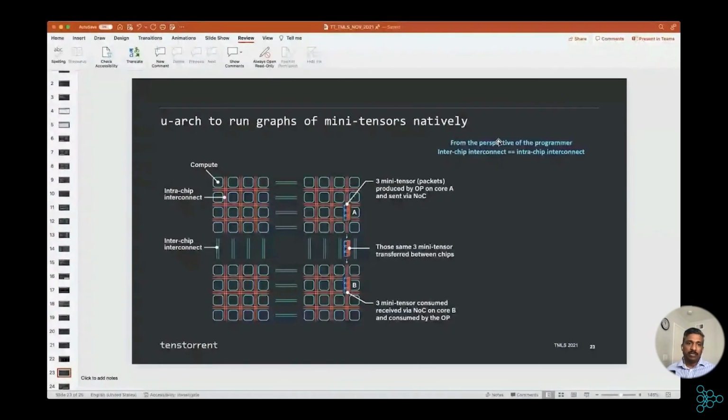This slide talks about the ability of our chip. The NOC inside our chip is not just doing the compute. In certain cases, you can also use our NOC as a switch, so there is no need for an external switch. If you see here, the packet comes from the tensor on the chip on the top, and it goes to the bottom. In this case, this chip acts like a network switch. So the NOC really has the capability to act like a switch. It provides a very native extension through the Ethernet. So we feel that the NOC really powers our scale-out solution.